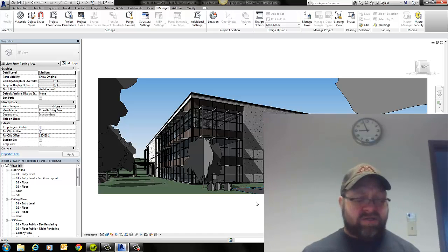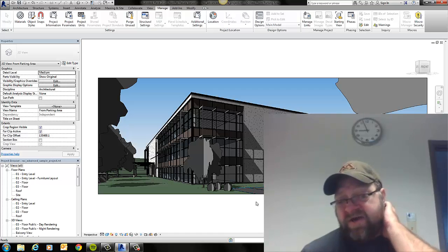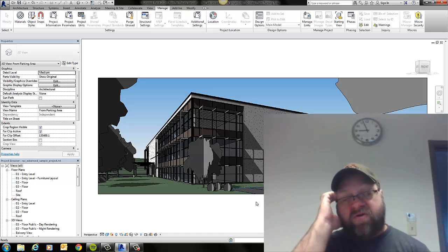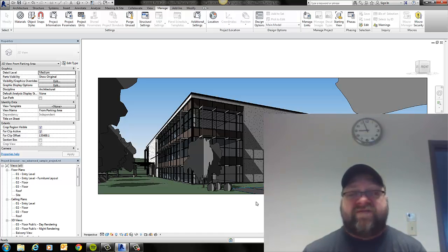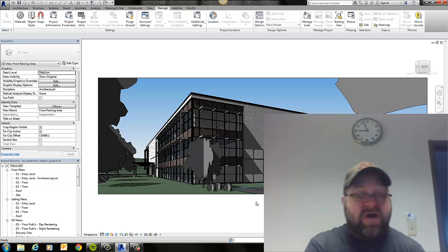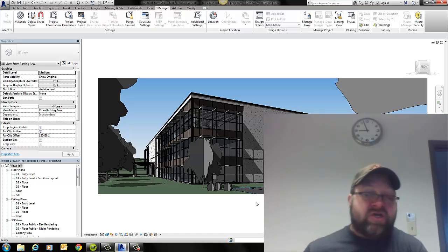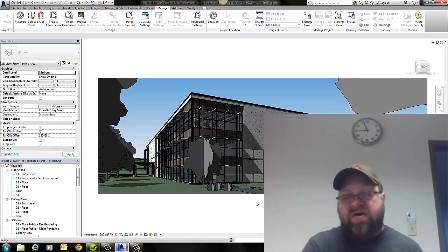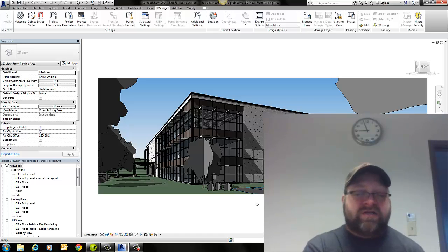Another way you might want to organize something is if you're working on a multifamily project. You might have units that you want to organize together, and you could group those in some way with layers, perhaps in AutoCAD, but in Revit, you use a tool called groups. AutoCAD has groups and blocks as well. So Revit does have ways to group items that aren't alike.